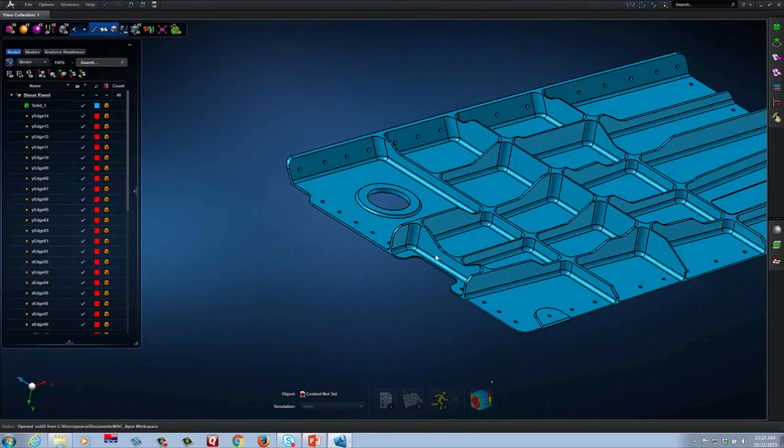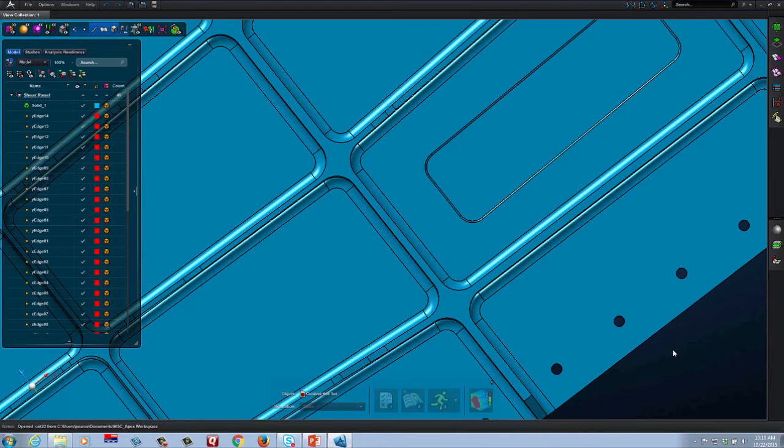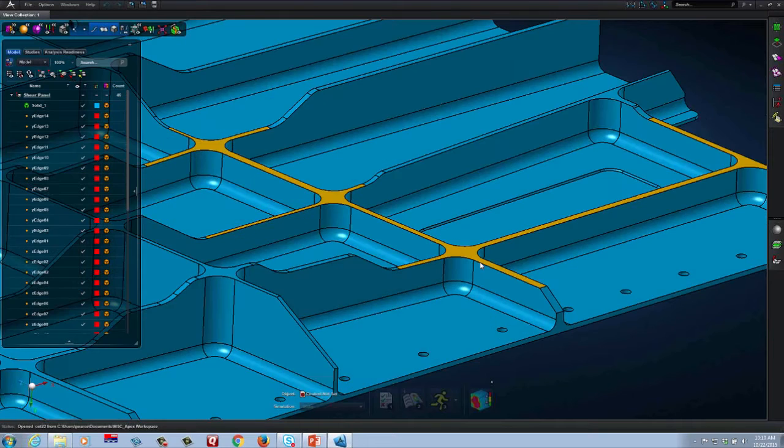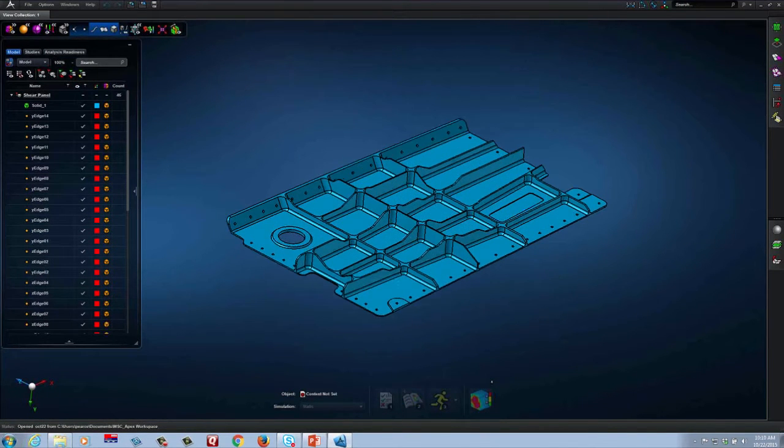All right. A couple of other things of interest here is if we look at these flanges, if we look at the top view, we can see that we actually have multiple thicknesses represented. The flanges are not all constant thickness. And if you can kind of visualize how they're going to extend and connect together, they don't always connect at a common intersection, which is not bad. I'm not saying there's anything really wrong with that, but especially if it's a little skinny area, it's going to produce poor elements and poor results. So my idealization, my engineering intent is to align those, because this is an idealized representation. This would be more or less a stiffness representation of this panel.